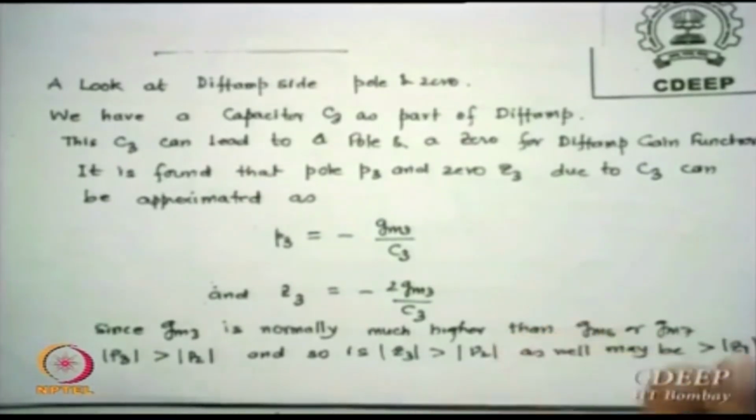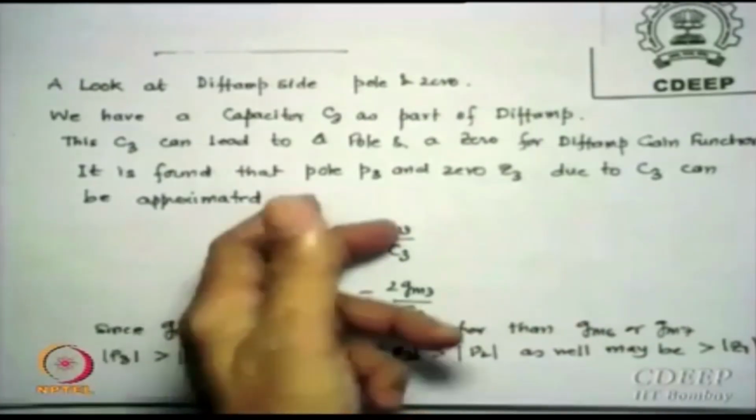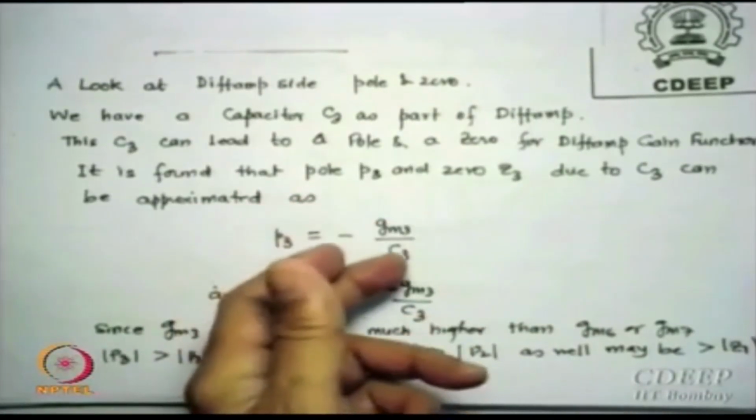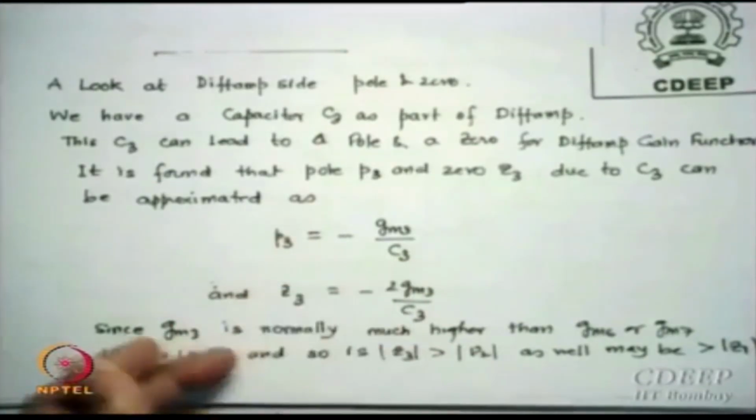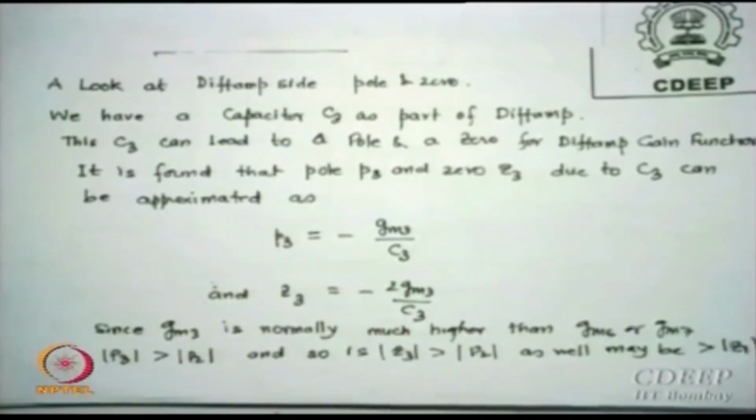But just to tell you where from we verify, just this substitution here, I must get Gm3, I must get this value of CGS whatever I get, and correspondingly evaluate these two and figure out where the poles and zeros are going, okay. And if that happens to be too far away, 1000 times, we don't care about it. So this is an issue which you must address, though as I say, if you don't address, nothing goes wrong in 99 cases, but as a designer I cannot accept anything without seeing it, though my intuition says it will not affect.